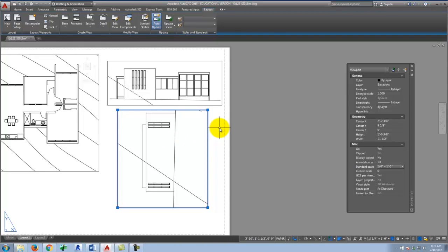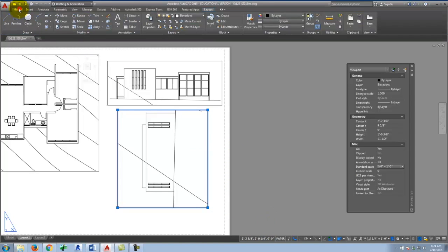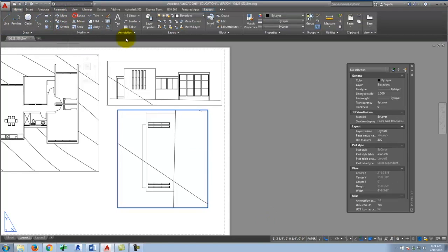Now, in the handout, under Part 3, I have you use a tool called MV Setup. Truth is that AutoCAD improved something in 2016. Things have changed. No surprise. I didn't discover this until this morning. Otherwise, I would have updated the handout, right? We don't have to use MV Setup anymore. We can just type Rotate, or go to our Home ribbon, select Rotate, and we can take this